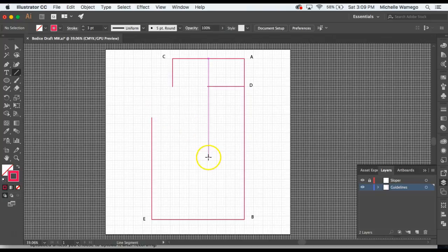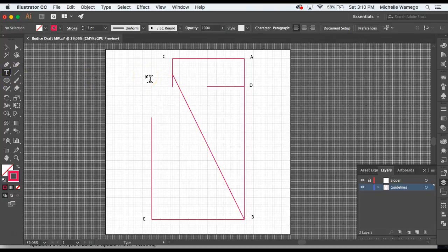This is our shoulder slope. So this line goes from B up to G, and my dimension is about 17.5 inches. Because this is at an odd angle, I would not know what to type in there, but I can read the dimensions here as I move this line to hit this guideline coming down from C. About as close as I can get is 17.49. I think that'll work. That will now be the point for G.